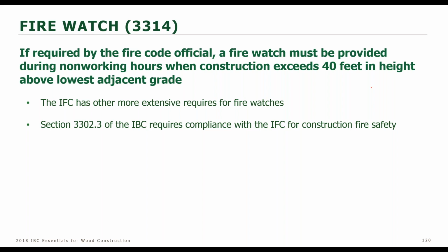There is a coalition that we belong to and greatly foster among designers, code officials, organizations to reduce construction fires. The building code, IBC, and the IFC fire code contain specific provisions for precautions during construction. Here's one, 3314, fire code official, if requires it, fire watch must be provided during non-working hours, even when construction exceeds 40 feet in height above lowest adjacent grade.